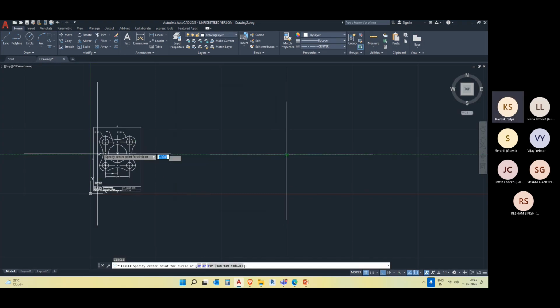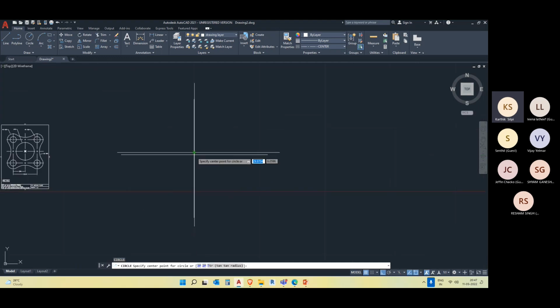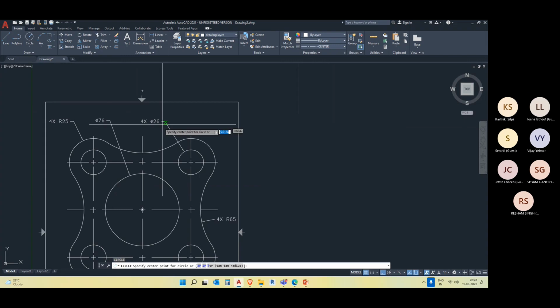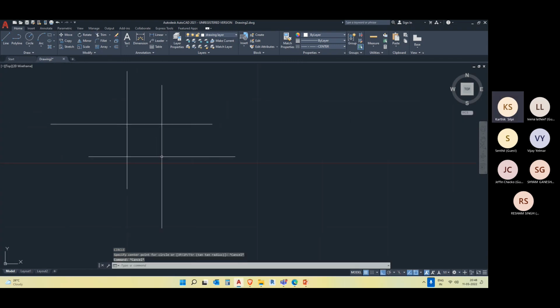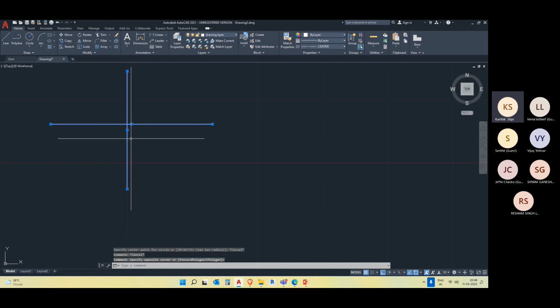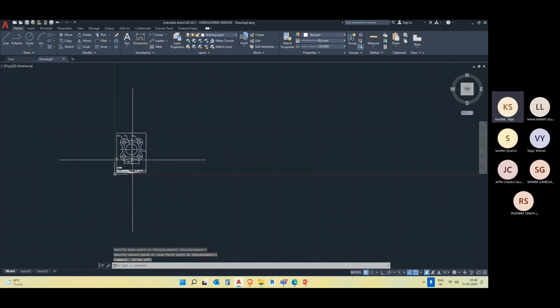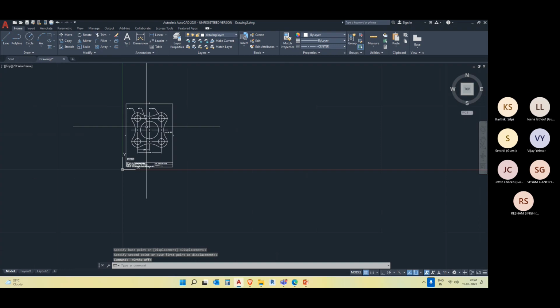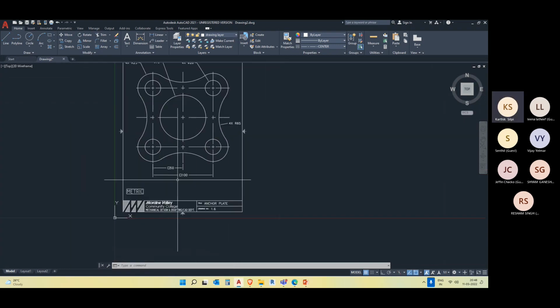So this is a minimized version, like the drawing is crunched. So we are seeing a small version of this. But let me draw as per the dimensions which they have mentioned. I'll just quickly move this somewhere else. So why we are getting this error is, as we imported the drawing to this AutoCAD environment, the drawing has shrunk to a dimension which is not the actual dimension.